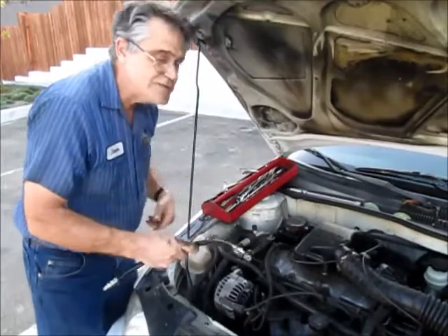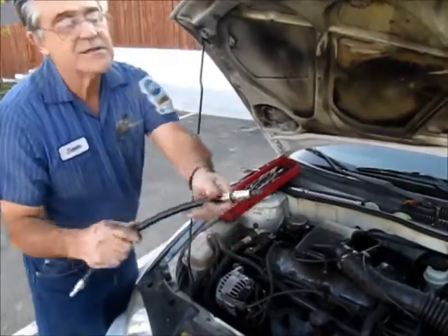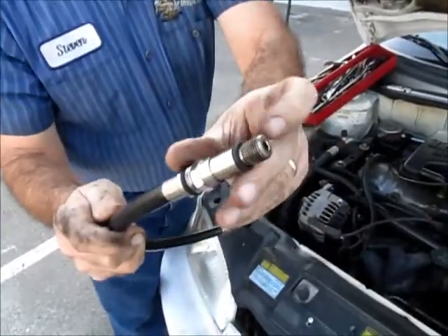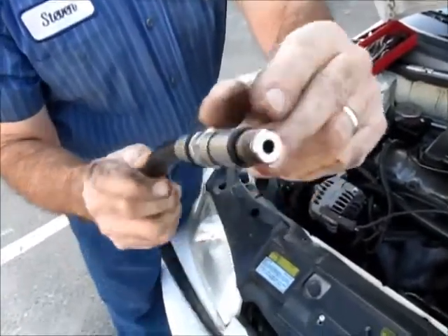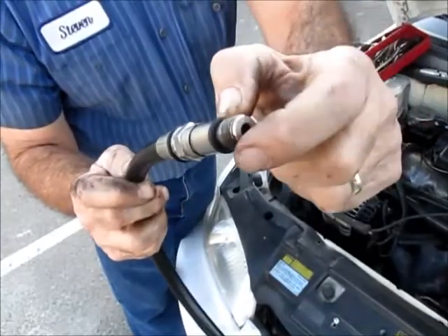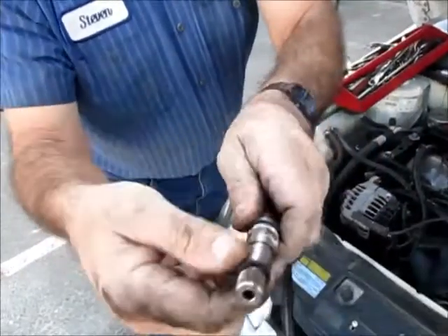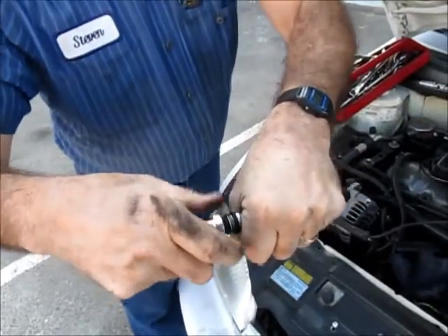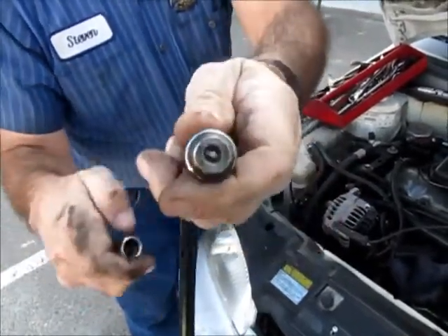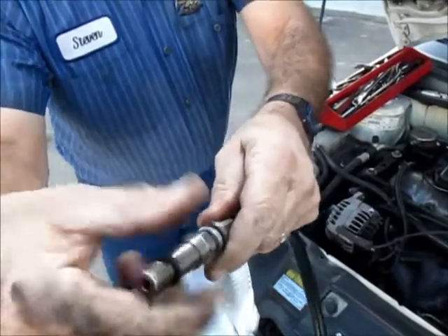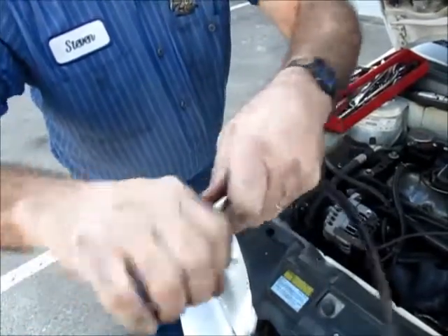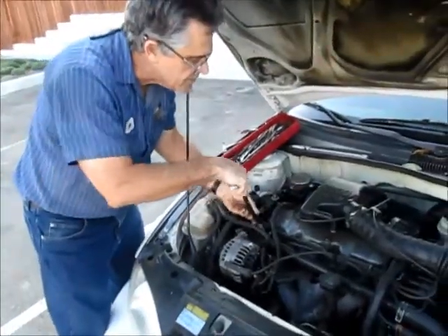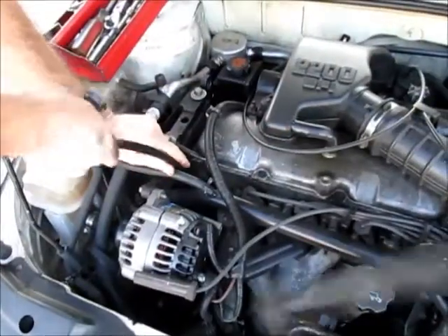In order to do that, you need to use your compression gauge. So you see that adapter. Make sure that the adapter is the right one. There's a check valve actually in here. Some of these have two check valves, and you want to make sure that you've only got one. And I think the one in here is installed. So there's your little Schrader valve. But anyway, just get this nice and tight. Okay, now we're going to put this in the spark plug hole. Okay, there we go. Gauge in the number 1 spark plug hole here.